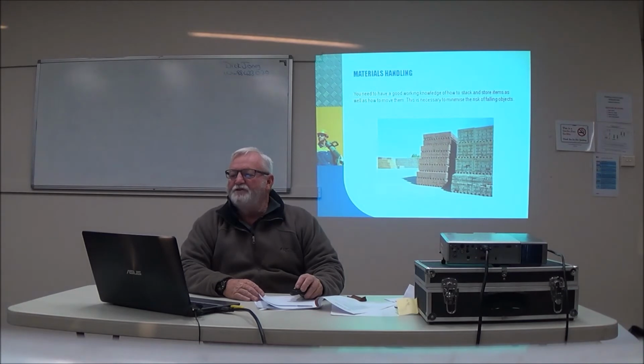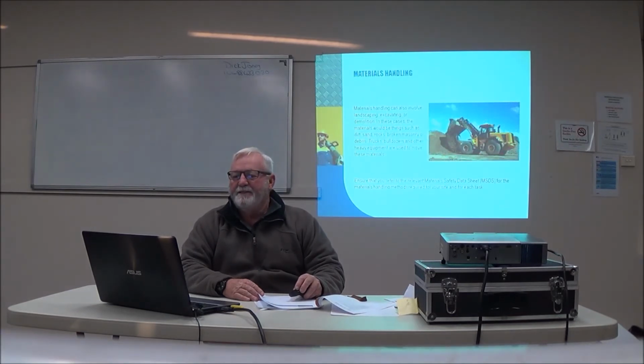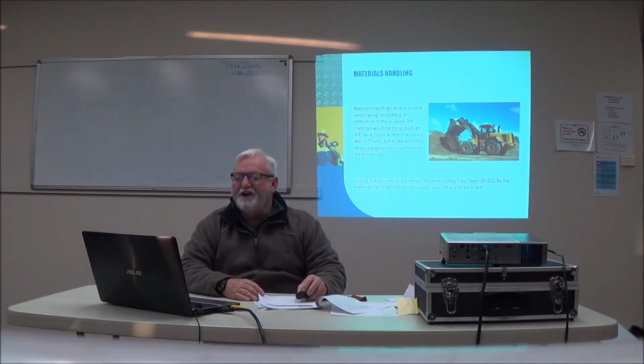You also need to have a good working knowledge of how to stack and store items as well as how to move them. This is necessary to minimise the risk of falling objects. Materials handling can also involve landscaping, excavation and/or demolition. In these cases, materials would be things such as dirt, sand, rocks, broken masonry or debris. Tools, bulldozers and other heavy equipment are used to move these materials. You should always ensure that you refer to the relevant material safety data sheet for materials handling methods required for your site and for each task.